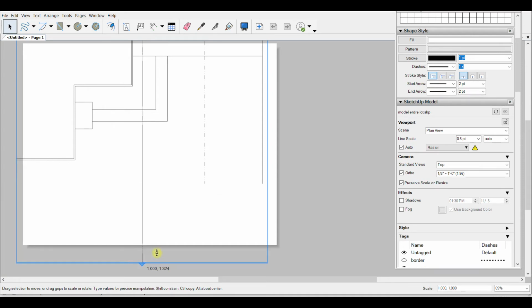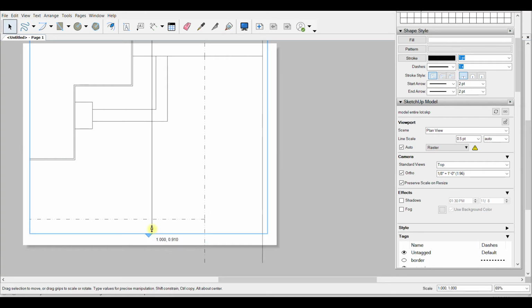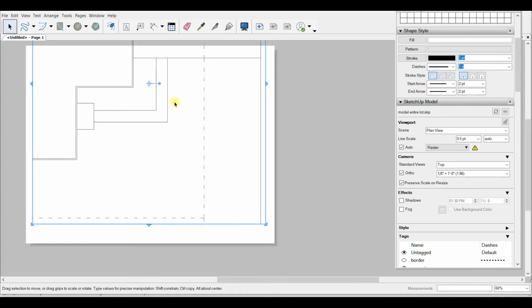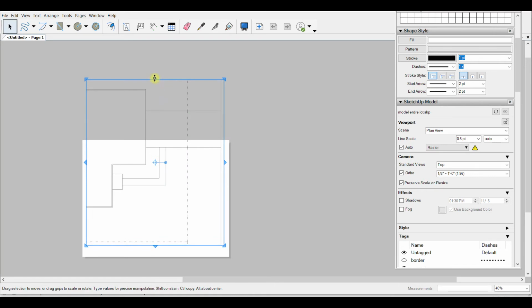Okay, you notice that the property line continues on to the next lot here, and the same thing at the other side of the building over there. We're going to make this a little bit shorter than the page. It's shorter than the page here. We're going to make this one shorter than the title block. Come up to here, and the top of the page. Whoa, where'd it go? Look at that. We're going to make it shorter than the page. Our drawing lines should never touch the page edge.